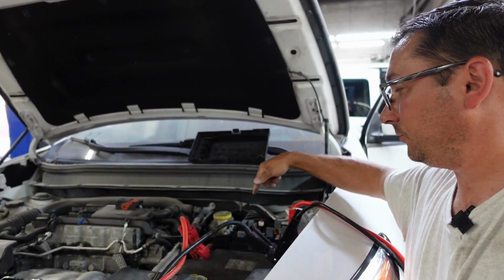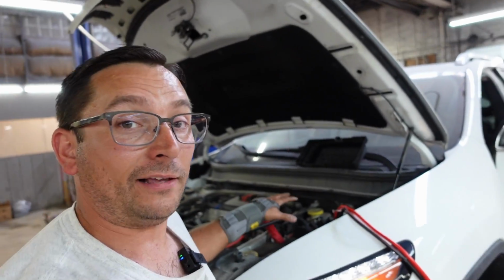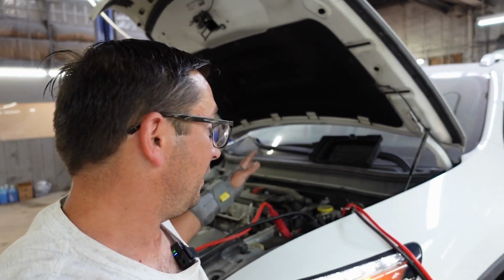I was checking the ASD circuit and I had 6.5 volts on there most of the time after the ASD relay was commanded off. So that was really interesting. And 6.5, 7 volts, well, that's exactly what our voltage drop was. We had some backfeeding through other circuits, other modules, causing all kinds of mischief.